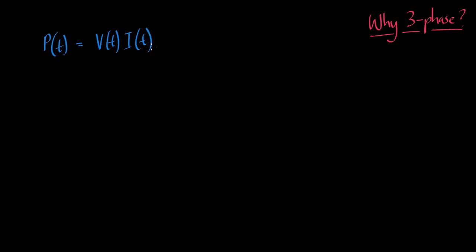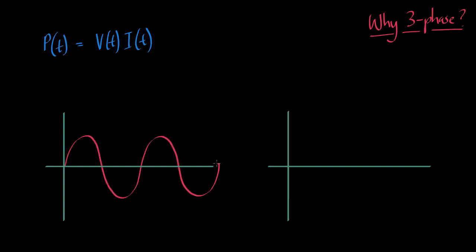Now that we have covered single-phase power, we can better understand why three-phase is the norm. Returning to the concept of instantaneous power is the product of voltage and current with respect to time. Single-phase circuits, therefore, with alternating voltages and currents, produce instantaneous power that oscillates at twice the system frequency. Assume that the current and voltage waveforms are overlaid.